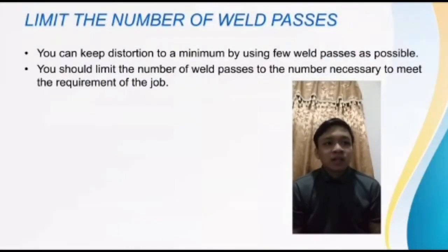Secondly, limit the number of weld passes. You can keep distortion to a minimum by using as few weld passes as possible. You should limit the number of weld passes to the number necessary to meet the requirement of the job.